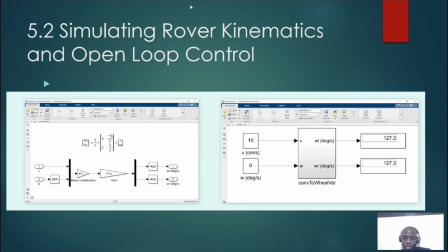left wheel is the desired linear velocity minus a term related to the turning rate and the wheelbase. And for the right wheel, it's plus the term because they are on opposite sides. These calculated wheel speeds are converted into a PWM signal, which controls the power sent to the motor, and adjusted by a minimum threshold to overcome static friction.